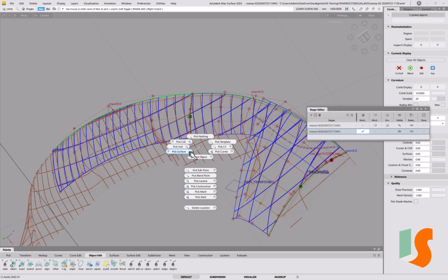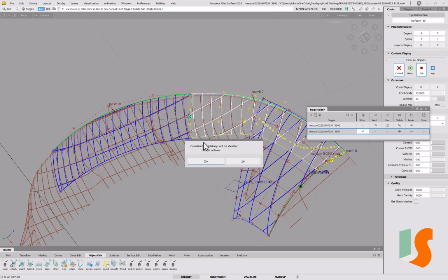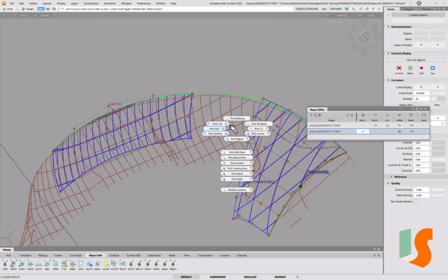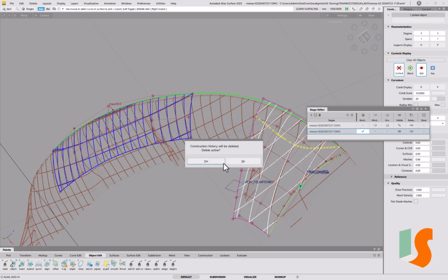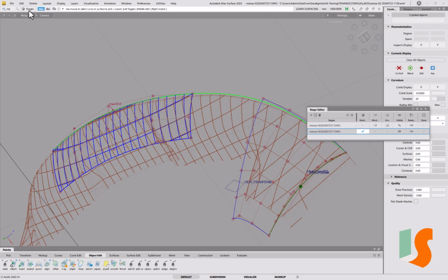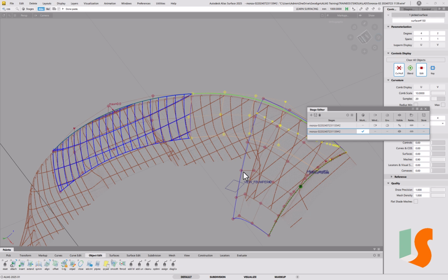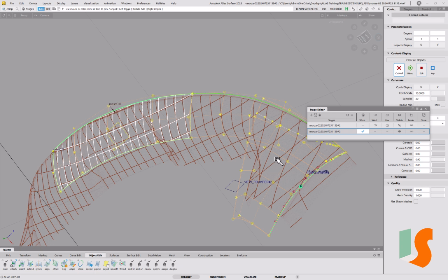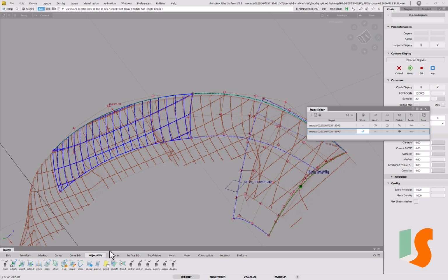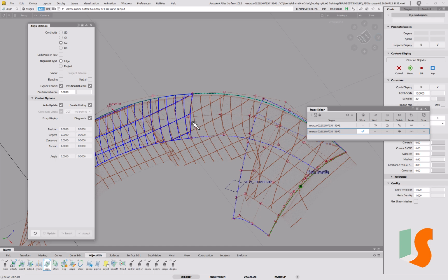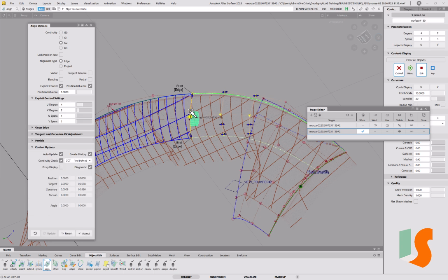Yep. So I'm going to delete this one, and we also want to delete the curves on surface in here because those are going to be stale. And then we should be able to do edit, paste, creation layer, and then let's just check 3 picked surfaces. Great, that's what we wanted. So I've no idea how those duplicates came into play, but maybe if I look back through the video I'll find out. Okay, so we want to align that.